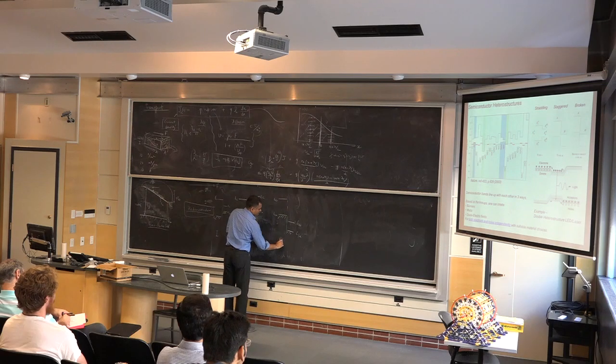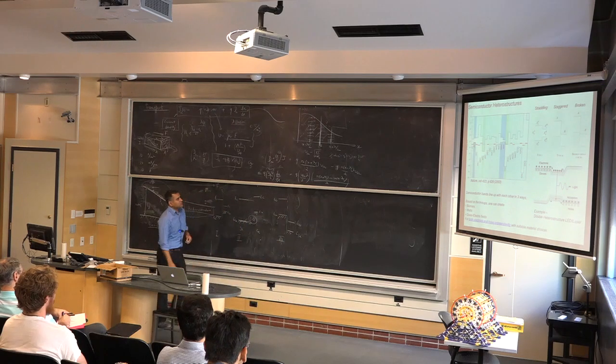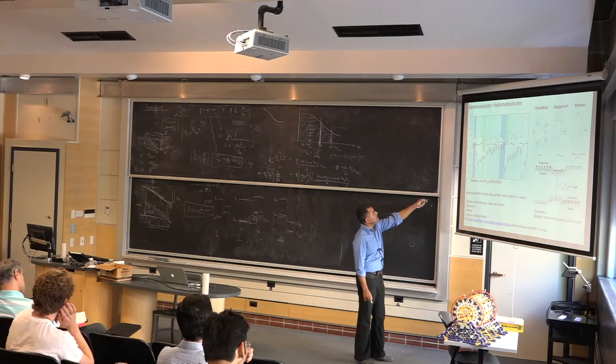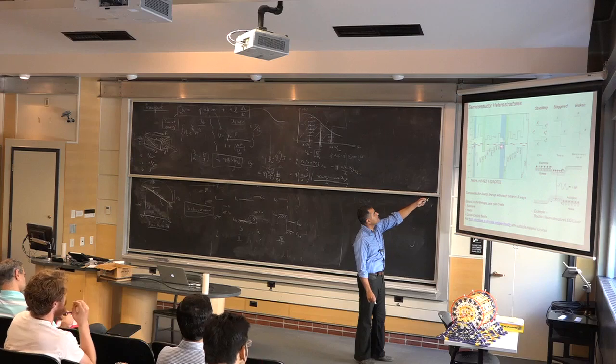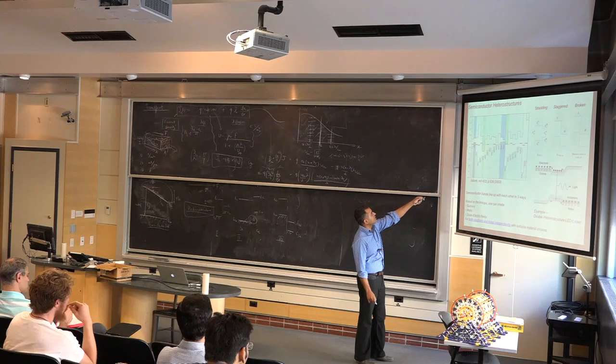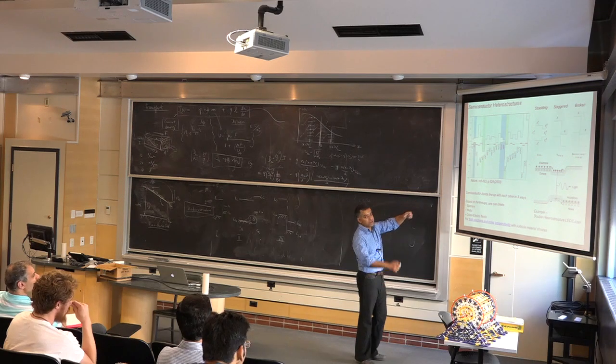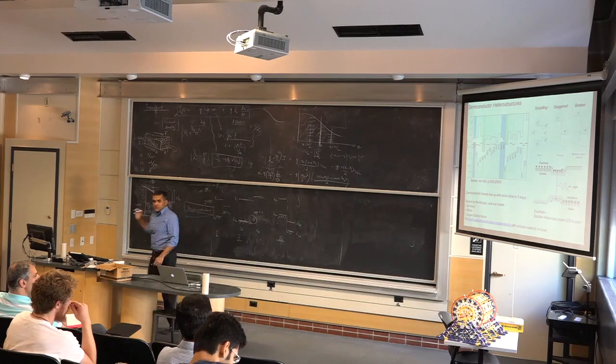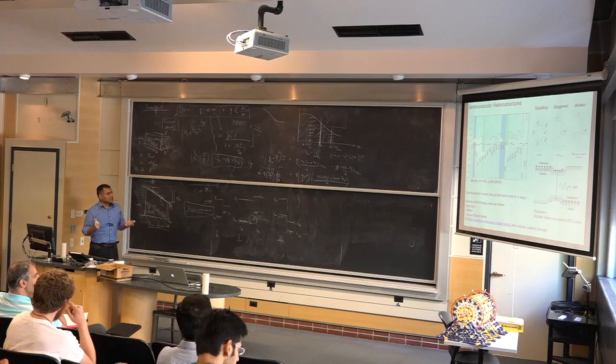Right? So that's type 3, broken gap material. One of the very important broken gap materials is when you take gallium antimonide, GaSb, and indium arsenide. You can see the valence band starts rising above the conduction band of indium arsenide. You can see they're broken gap. So all of them have very important uses, some transistors, some lasers, some other things.